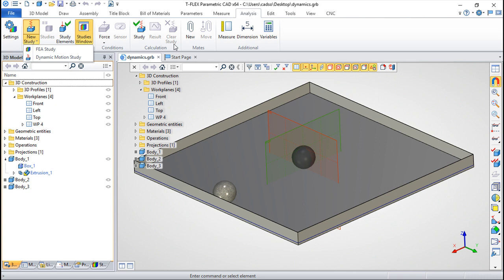We can analyze also performance times of these same mechanical systems, like the time to reach a target point, vibrations to settle, etc., or analyze forces building up in components of a mechanical system during motion, reaction forces that support joints, whatever. Okay, we have a lot of possibilities. There are some rules and some common elements in all the studies, but let us briefly describe how to use this. So the first step is to go into this option here and create a new study.